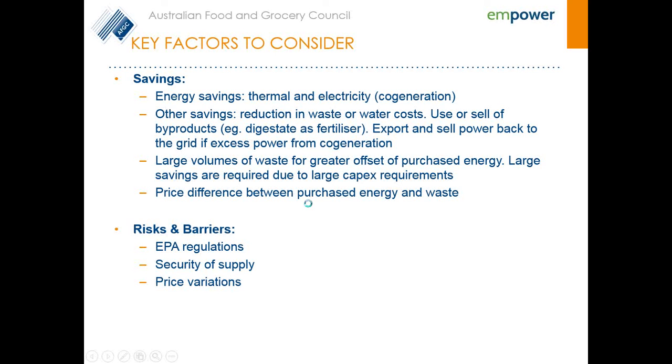Technology options. Again, how the technology integrates with your existing facility. When talking about biomass, it's really important to consider layout constraints, because the larger the size of the equipment, it's not just the boiler that increases in size, but also all the storage and conveyors and handling equipment that is associated with that. That can require a lot of space. If you already have some constraints in that regard, then it becomes a barrier.